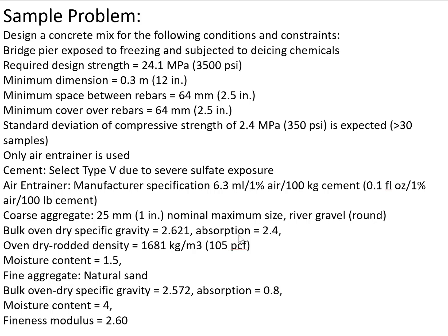For high early strength cement, the cement powders are finer because when the particles are finer, they have larger surface area, and so the hydration process will be faster and the strength is developed in a faster manner. The third type only occupies about 4% of the total cement production in the United States.